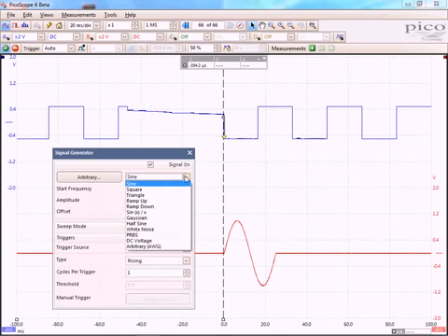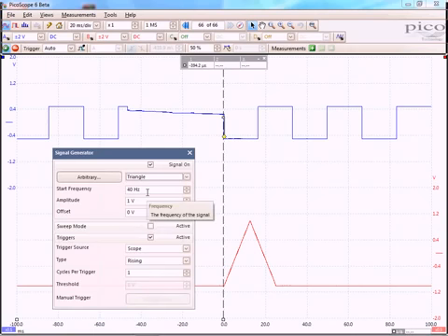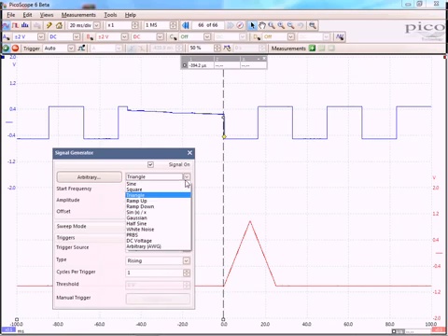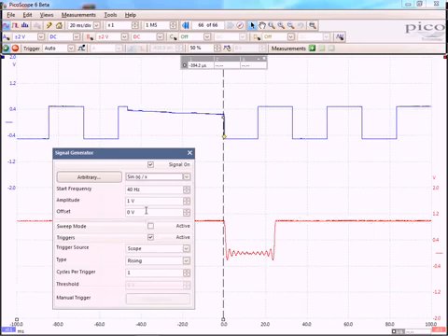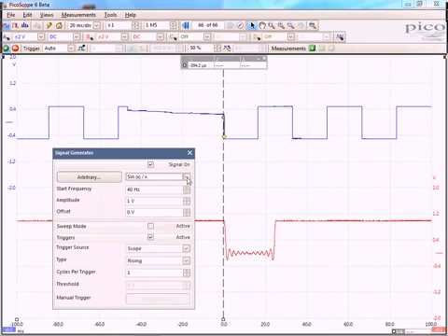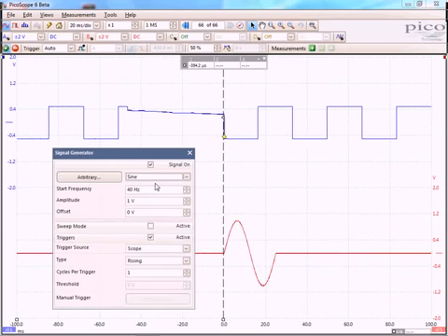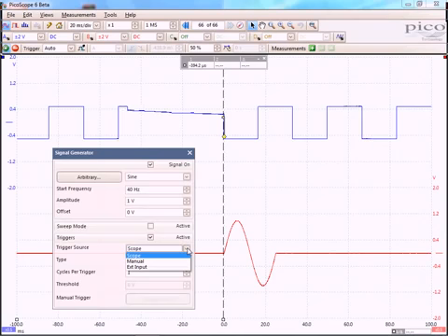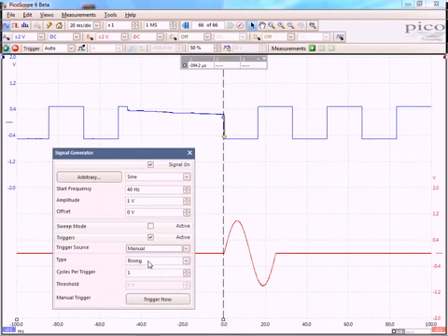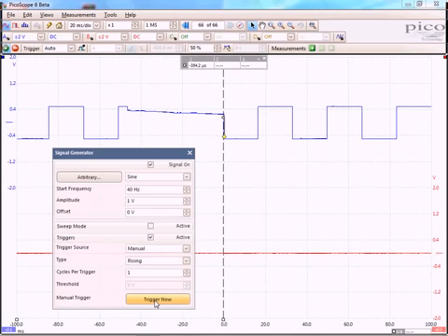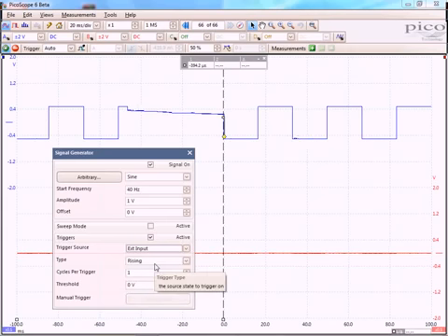I can change the signal type by using a square or triangle or sin x over x. This is all customizable. I can also use the signal generator trigger with using a manual input. Alternatively, I can use the external input of a scope.